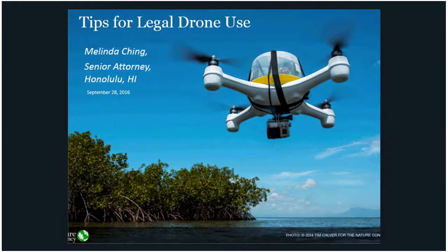But I've gone from using Landsat down to Digital Globe, the 1 meter and 50 centimeter stuff, and there's a lot more to think about, and this is going into general remote sensing, in terms of just the quantity of data that you're dealing with. You've got a couple of hundred megabytes to many gigabytes. It's a real headache, and then you've got things such as which way the satellite or the sensor is pointing at that time, where the shadows are, and so the headaches just get exponential.